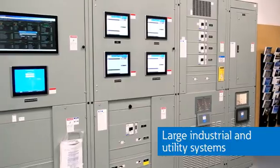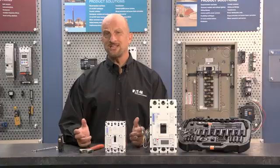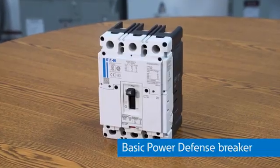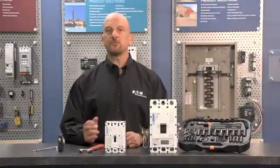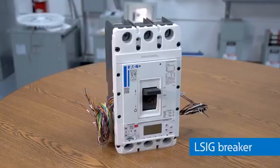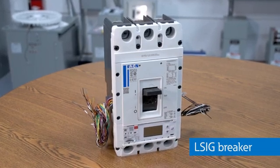circuit conditions. There are many types and sizes of circuit breakers used on power systems, from residential to large industrial and utility systems. Basically, you can categorize circuit breakers as either thermomagnetic, designed to trip on their own during overcurrent conditions, or circuit breakers that trip when another device like a relay or trip unit tells them to trip. The more advanced breakers can have many adjustments and settings that offer better coordination and selectivity with other protective devices. We will focus this video on 4 types of circuit breakers: miniature circuit breakers, molded case circuit breakers, insulated case breakers, and power circuit breakers.